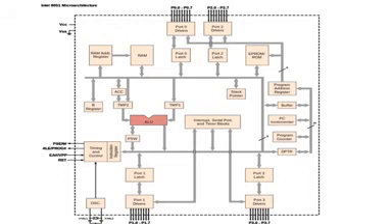And for example, you can also take your microwave oven. Even in that you give some time delay. In such applications we use this. And the counter is used to count events. So in short, timers are used to create some delay between any 2 actions, whereas counters are used to count events. These are about timers and counters. The timer is of 16 bit. You have 2 timers in the 8051, each of 16 bit size, that is timer 0 and timer 1.